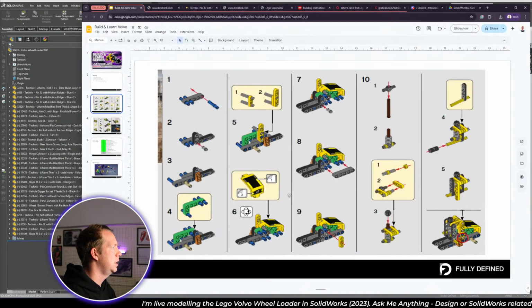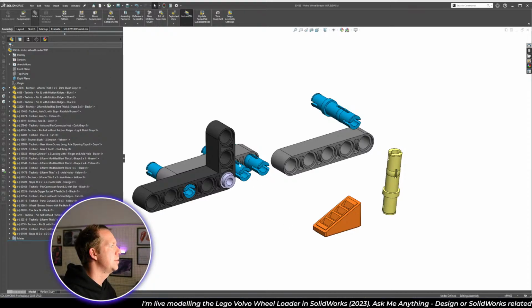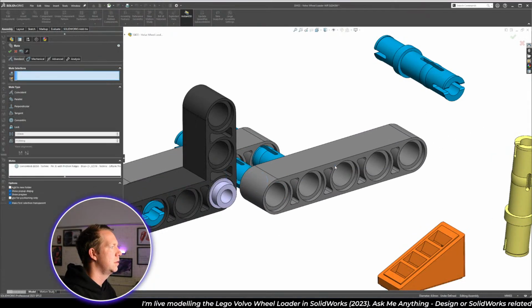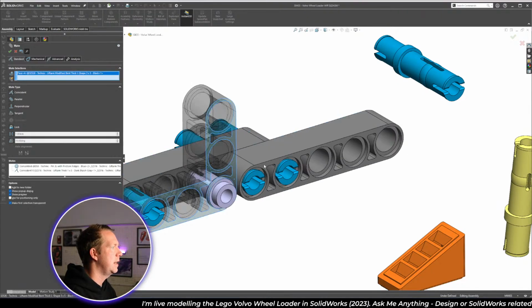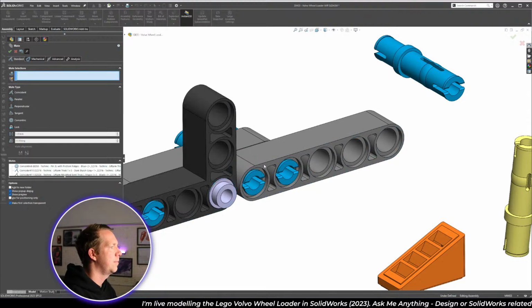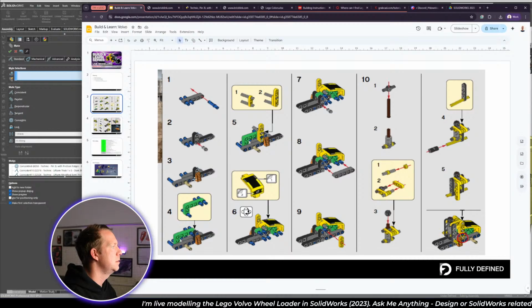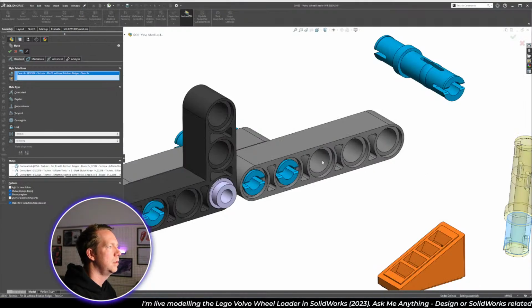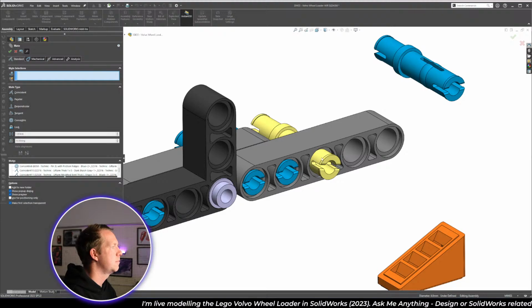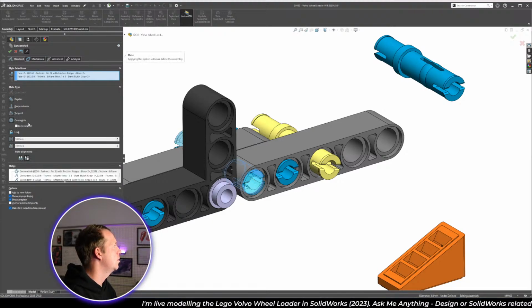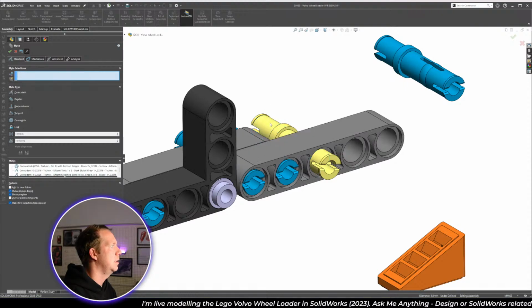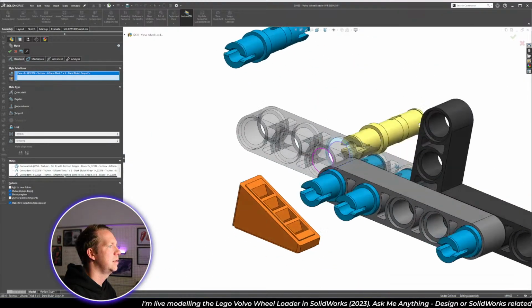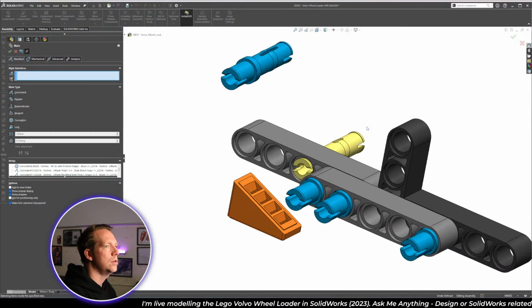All right, so the assembly, the grey one's going to match these holes. And it's going to match this face. So it has a little gap. The tan piece sits in the middle, like that. We'll just go back to make that lock rotation. Not that one, this one. And then we're going to select this face to get those combined.